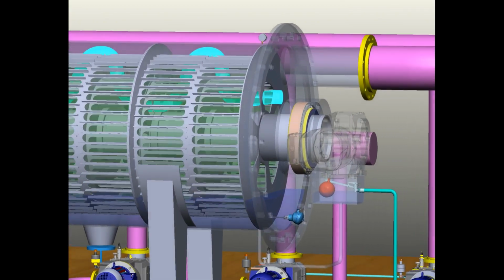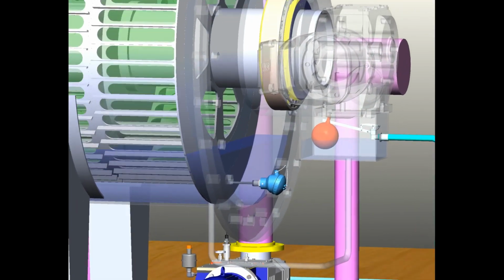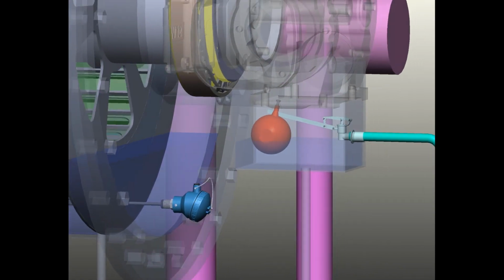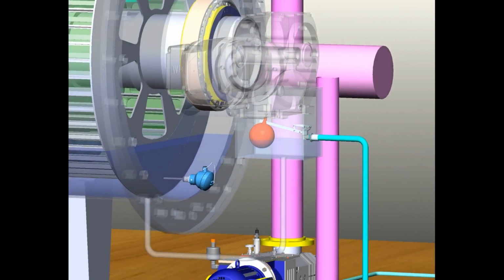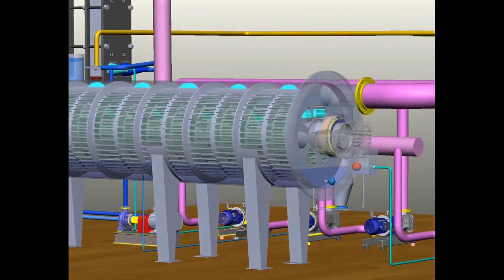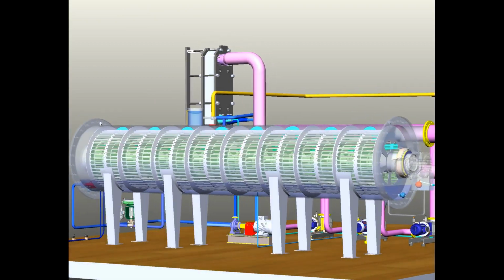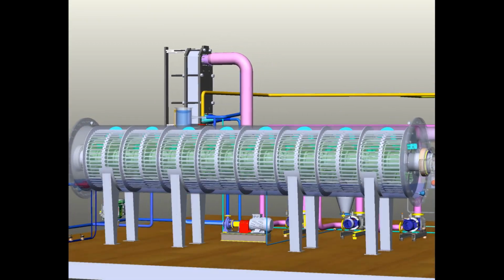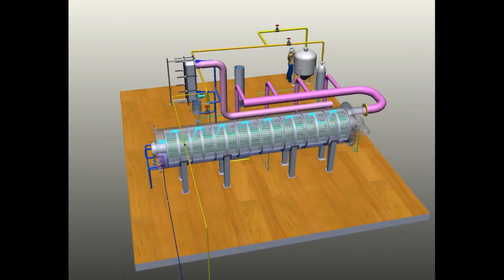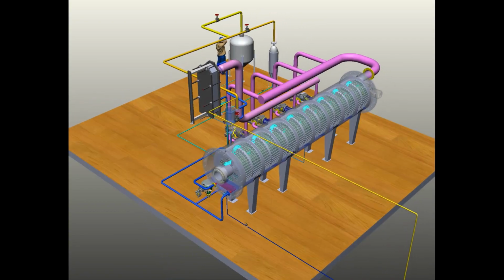In the lower part of the body, water with a low deuterium content flows towards the steam flow. The steam generated by the heating tubes, colliding with the developed wetted surface of the nozzles, exchanges molecules of light and heavy water on it, enriching itself with light water. The film enriched with heavy water on the surface of the nozzles, periodically immersed in running water, enriches it with heavy water. Thus, the vapor is cleared of molecules with deuterium and, after condensation, light water is formed.